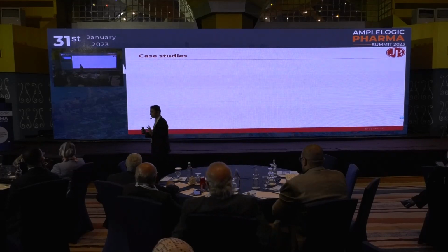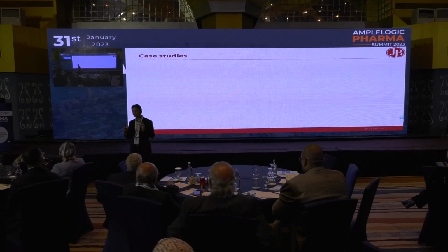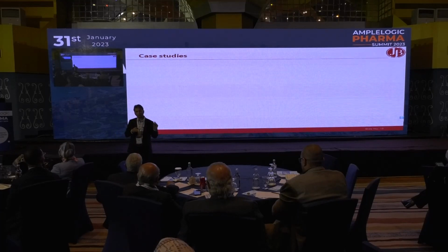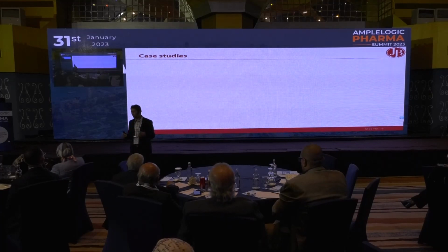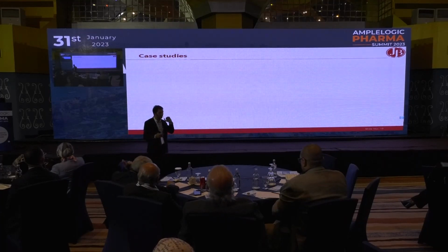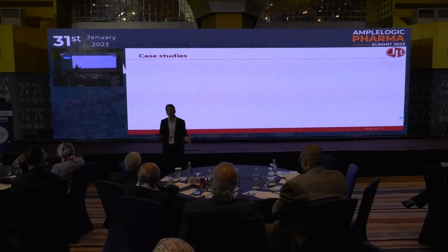And the third risk was they installed a sensor outside, near the cockpit, because they have to scale the position of the aircraft. So they have to position the sensor outside the aircraft, right in the front near the cockpit, which was a wrong position, because any balloon in the air or any bird hit can damage the sensor easily.